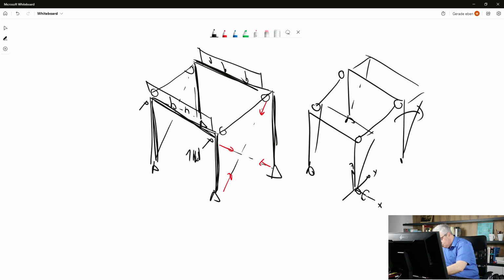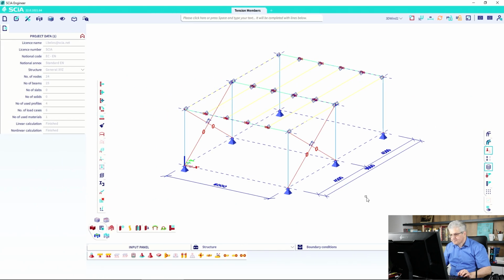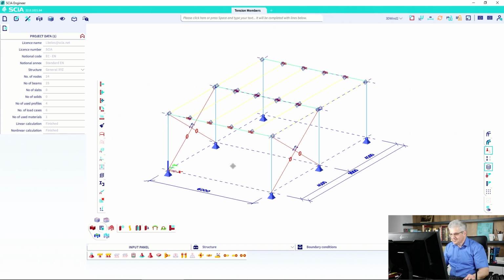Then I create a small spring around the x and y axis with 0.0001 meganewton meter per radian. This is a very weak spring. So if it is loaded, then it goes down, but if it is not loaded, then it stabilizes my structure enough. But I didn't get this message now, so probably the solver team did something so that it doesn't happen.